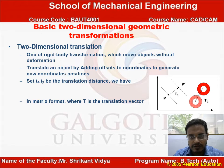So we will go for two-dimensional transformation. Two-dimensional transformation is very applicable in numerous applications like geometric modeling, manipulation of size, shape, and location. Transformation is used to generate a surface also. Transformation is of two kinds: modeling transformation and visual transformation. Modeling transformation alters the coordinates of the object. The basic operations are scaling, translation, rotation, and a combination of one or more of these.